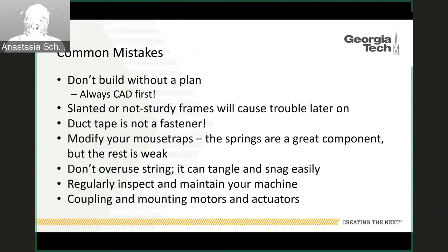Another mistake that we see is overusing string, especially if you have some sort of pulley system. You don't want any more string than necessary. It's really easy to tangle and snag, especially with all the moving parts. You always want to regularly inspect and maintain your machine. The lifetimes on these machines are not very long at all, so you can definitely expect things to break even if you're not really doing anything wrong. So you want to check and make sure, try to avoid that if you can, especially before a competition.